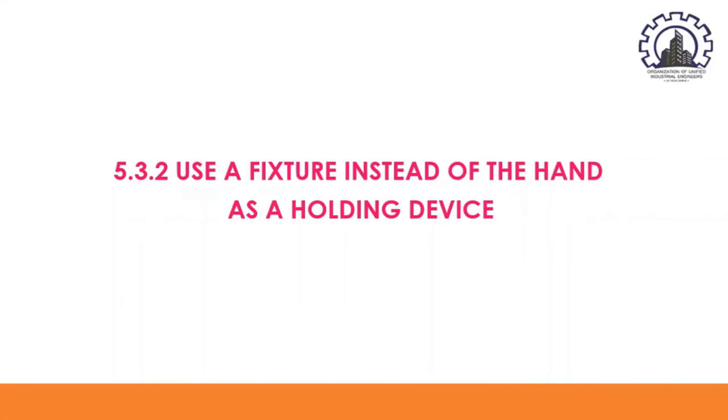One example is when we did the two-hand process chart, wherein it was stated that when the hand is only holding a material, then it is considered ineffective. That is why a fixture is designed to hold the work satisfactorily, thus allowing both hands to do useful work.